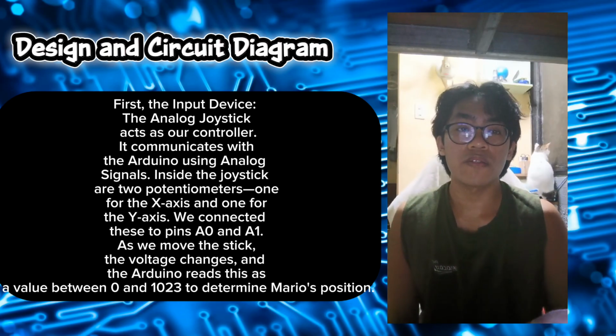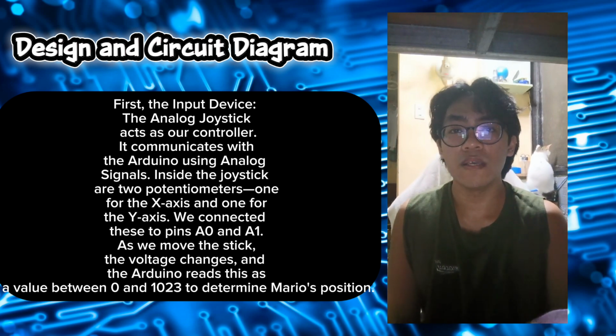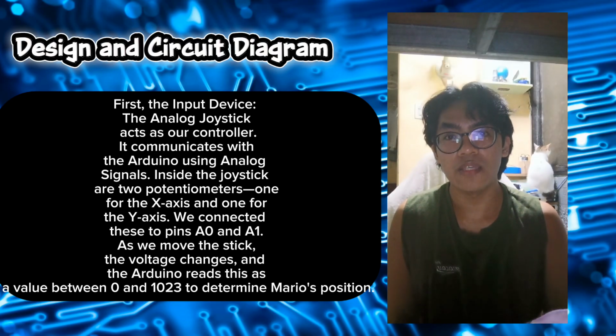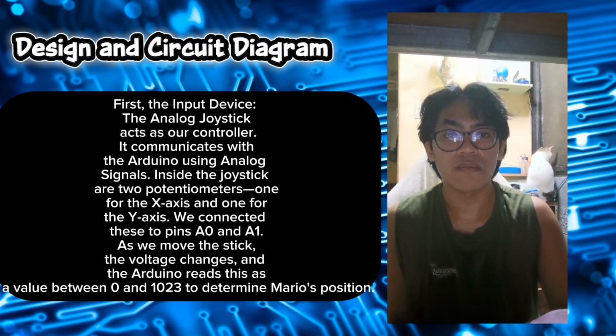Inside the joystick are two potentiometers, one for the X axis and one for the Y axis. We connected these pins to A0 and A1. As we move the stick, the voltage changes, and the Arduino reads this as a value between 0 and 1023 to determine Mario's position.